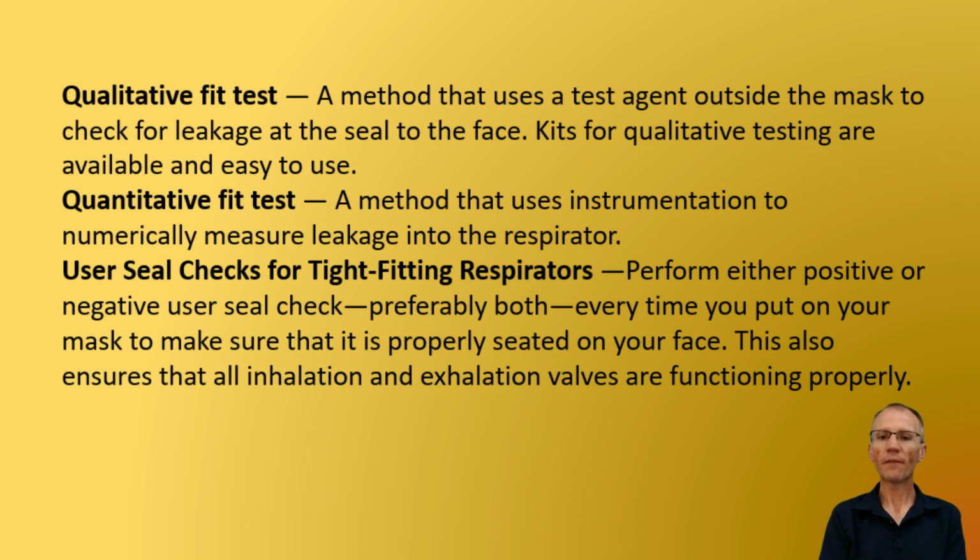I definitely want everybody to remember these two types of fit tests, especially for exam prep. A qualitative fit test is a method that uses a test agent outside of the mask to check for leakage at the seal to the face. Kits for qualitative testing are available and easy to use. Now the quantitative fit test is a method that uses instrumentation to numerically measure leakage into the respirator.